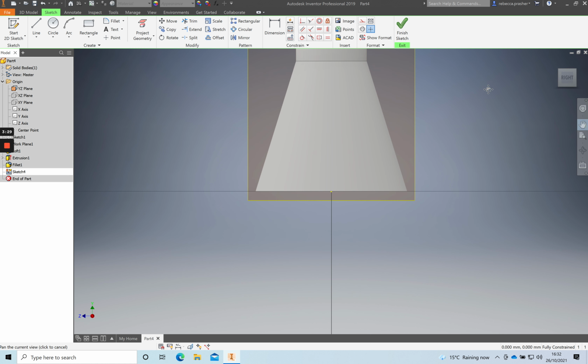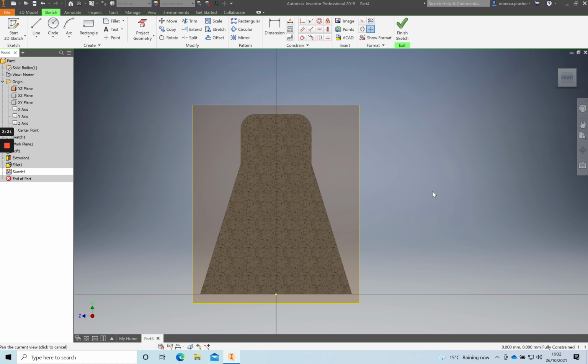Now, using F7 on the keyboard to cut the shape, we are going to draw the triangle at the bottom that will allow us to cut it. So I'm going to click the line tool. I'm going to do the edge all the way along the bottom. Now, I'm not too worried about the length at the moment, but I do want to make sure that the degrees, so pressing the tab key, is set to 20.